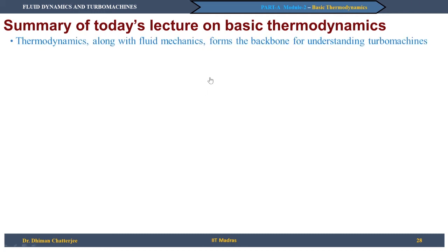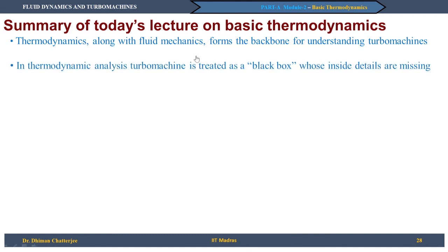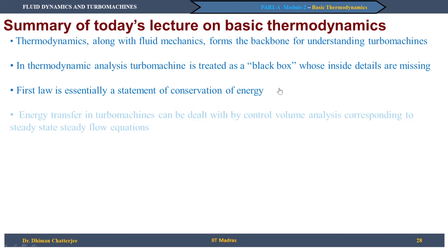We talked about thermodynamics, and we found that thermodynamics along with fluid mechanics forms the backbone for understanding turbomachines. In thermodynamic analysis, a turbomachine is treated as a black box whose inside details are missing. We talk only about the energy interactions. The first law is essentially a statement of the conservation of energy. We applied it for the control volume approach, and energy transfer in turbomachines can be dealt with control volume analysis corresponding to steady state steady flow equations.